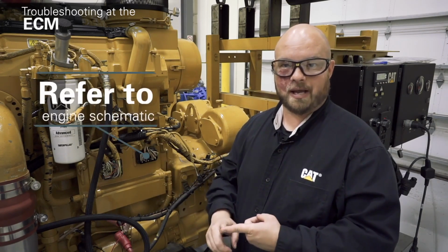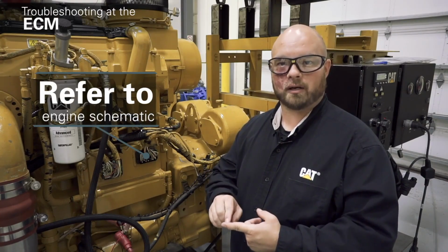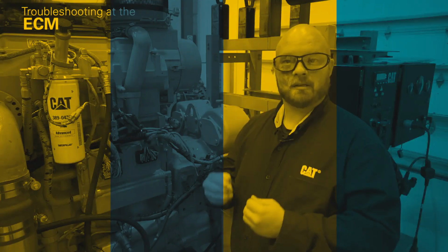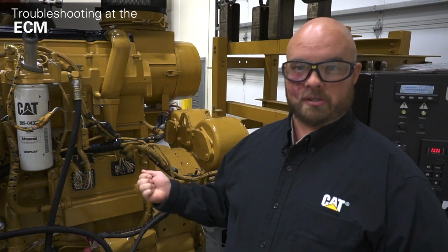So first thing I need to do is look up the schematic for my engine here, okay? We need to find out where our signal wire from the sensor enters into the ECM. Which connector, which wire do we go at? So we've identified that. Remember, we're dealing with a -4 voltage below normal code, and we've eliminated the sensor as being a suspect here. So at this point, we want to make that opposite condition again, only this time we do it at the ECM.